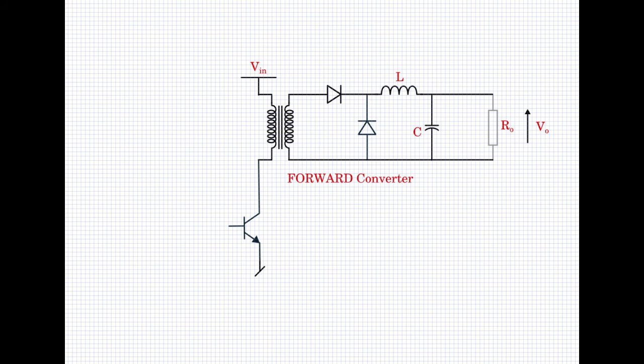After having placed the transformer here, let us now assign the dot polarities to the primary and the secondary. So let us say that is the dot end for the primary, and likewise this is the dot end for the secondary. Assigning dot polarities is very important. You have to do that for every transformer or every coupled component that you would have. What it basically indicates is the relative polarities of the various windings.